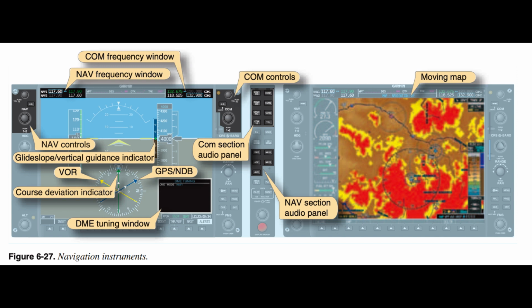Cross-check. Once the initial attitude changes have been made, the pilot should verify the performance of the aircraft. Cross-checking the control and performance instruments requires the pilot to visually scan the instruments, as well as interpret the indications. All the instruments must be utilized collectively in order to develop a full understanding of the aircraft attitude. During the cross-check, the pilot needs to determine the magnitude of any deviations and determine how much of a change is required. All changes are then made based on the control instrument indications.